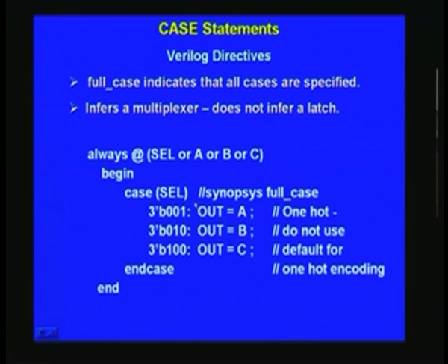how this does. So there is a directive called synopsys full_case. This looks like a comment, but it is a directive, it is more than a comment, right? So take care that you do not put this as any of your comments. If you do, you will get into trouble, right? What all it signifies for the synthesis tool or even a compiler is that we have given only a partial list here, we have not given the entire thing, but you regard it as a full case.